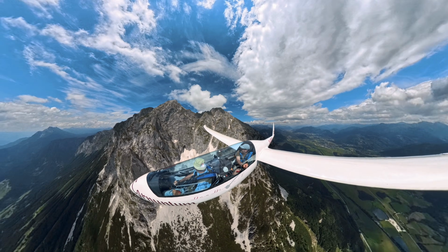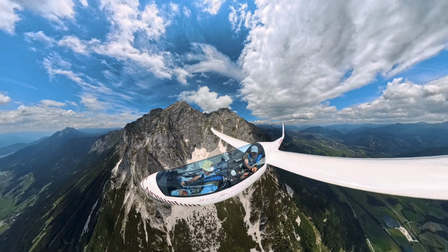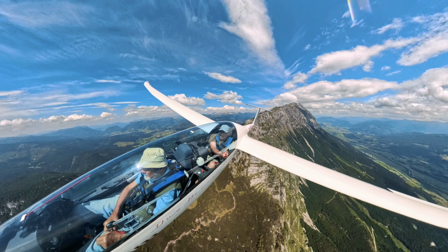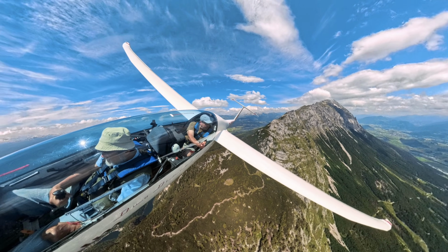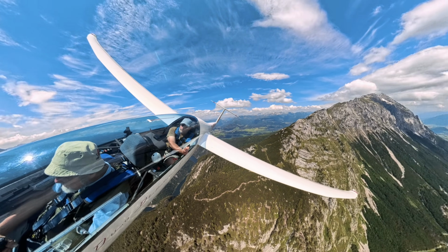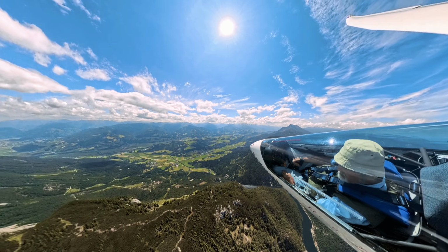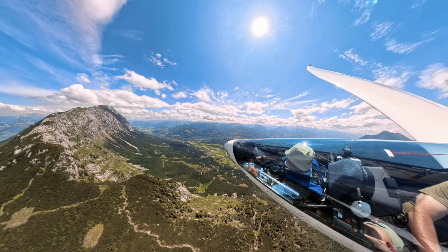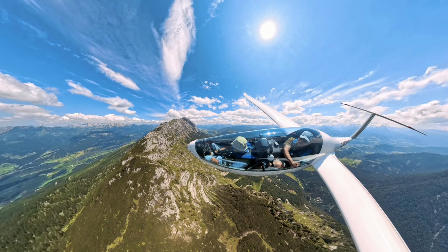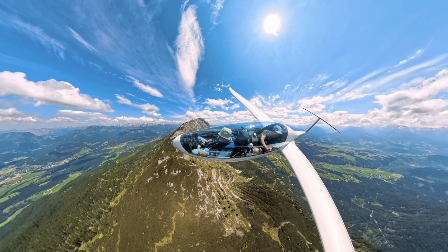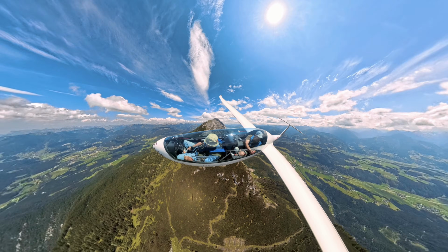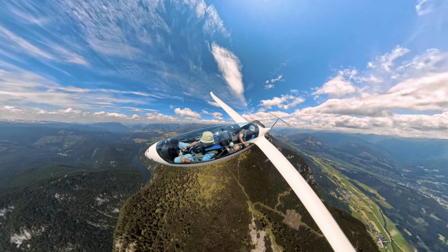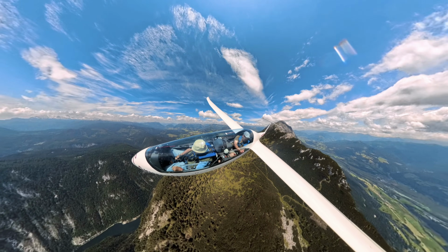Okay, let's summarize this. Rolling a glider has a secondary unwanted effect: it yaws in the opposite direction. To compensate, we have to use the rudder in the same direction as the roll. Only by applying a coordinated input of aileron and rudder in the same direction can we ensure a smooth and balanced turn without unnecessary yaw. This is quite a challenging task and can be mastered more effectively with lots of practice. The better we coordinate, the more efficiently we slice through the air.